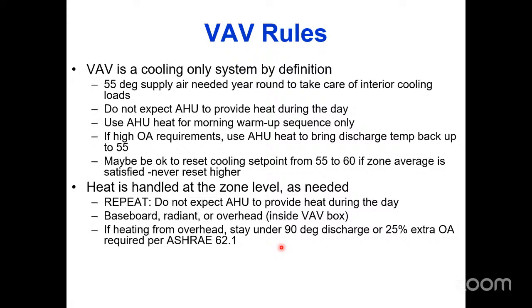And your discharge air temperature cannot be more than 15 degrees above the space temperature. So if you set your space temperature for 75 degrees, your maximum discharge is 90. If you set your space temperature for 70, your maximum discharge is 85. Essentially, if the air is too hot, it just hugs the ceiling longer. The way you satisfy the thermostat is by heating the wall all the way down slowly over a long period of time. The floor stays cold and you don't get any mixing of the upper part and the lower part. So you need less heat in order to do that.